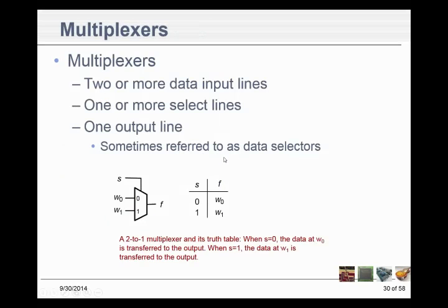Multiplexers. So we just switched topics here. This one's the one that I think is more important than anything else in this whole set of slides, the multiplexers. Here's a 2-input multiplexer. With a 2-input multiplexer, here's our two inputs, W0 and W1. That's our data input. It takes 1 bit to decide between 2 bits, or 2 values. So we have one selector, and that one selector, when it's 0, is going to take W0 and connect it down to the output, F. And when the selector bit is 1, it's going to take W1 and connect it to the output bit. Just like this is showing.